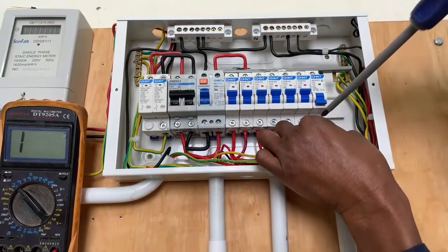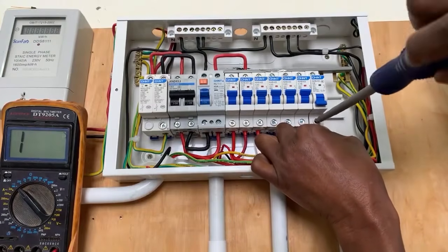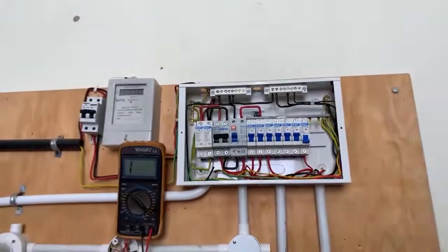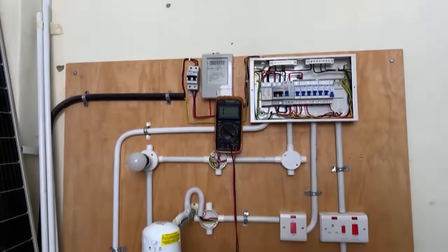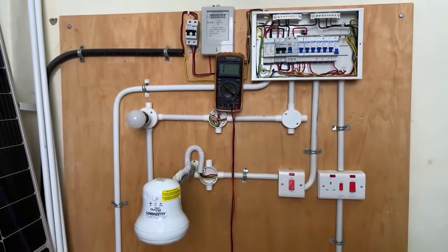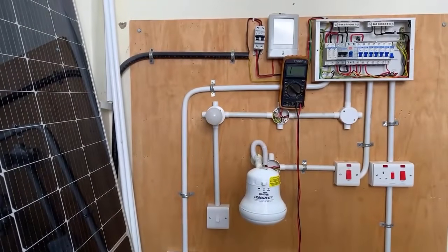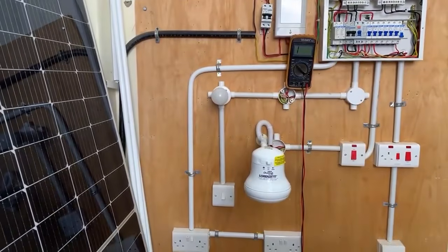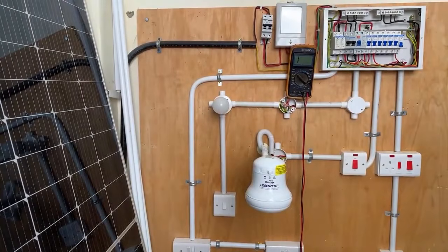Very simple for us. We connect it and we screw. So this will be the first time that we'll be putting the line on, or the MCB on, when we have rectified the problem. We have used our digital multimeter to test for continuity. We confirmed that there was continuity. And so we are going to switch it back on and test for the presence of electricity in the light circuit, or in that circuit.